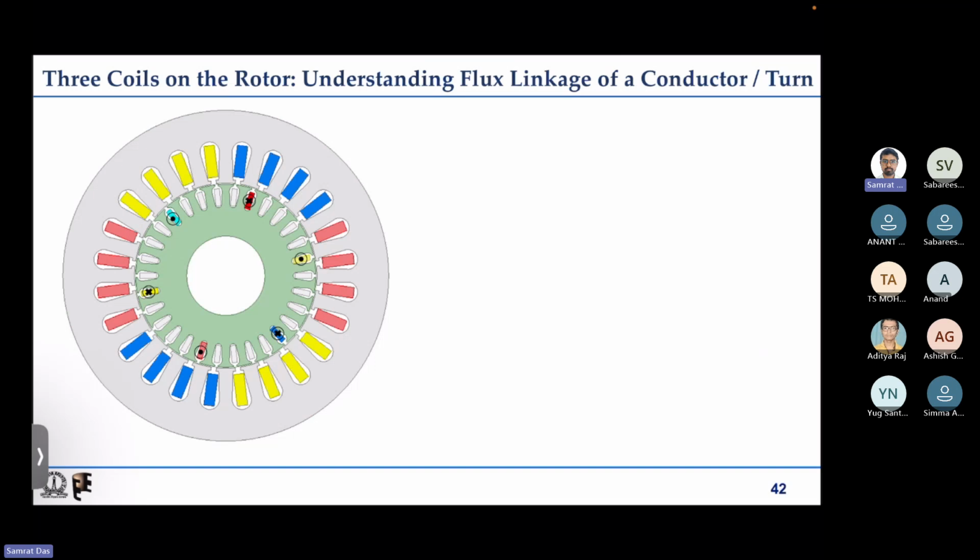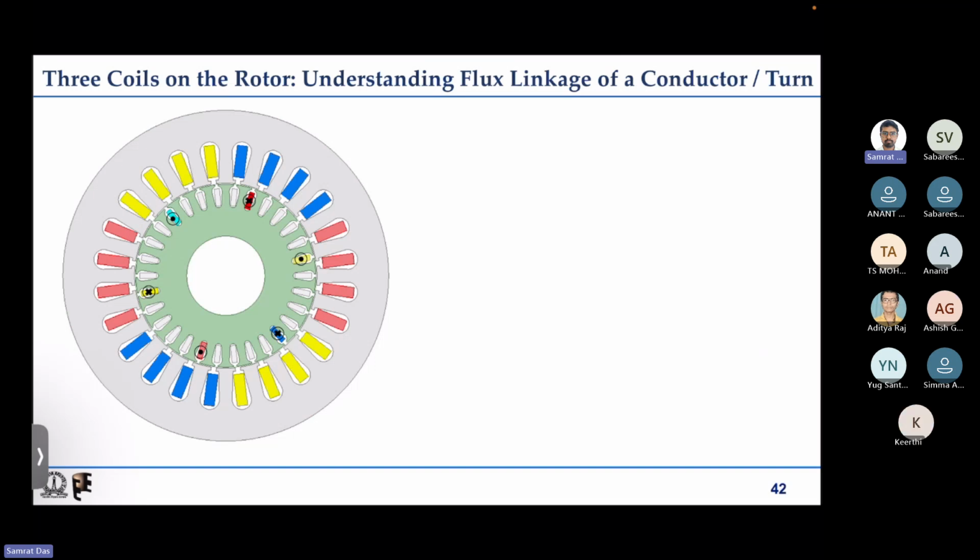Now we try to understand, is it actually necessary? So what did we discuss till now? We understood that we can create a rotating magnetic field from the stator by giving some three-phase current excitation into the stator winding. In order to generate continuous torque, the rotor field also needs to run at 3000 rpm for this specific case. So the stator we are giving 50 Hz, so the Fs runs at 3000 rpm.